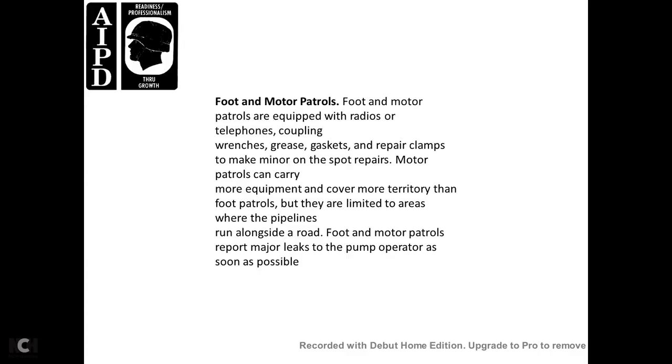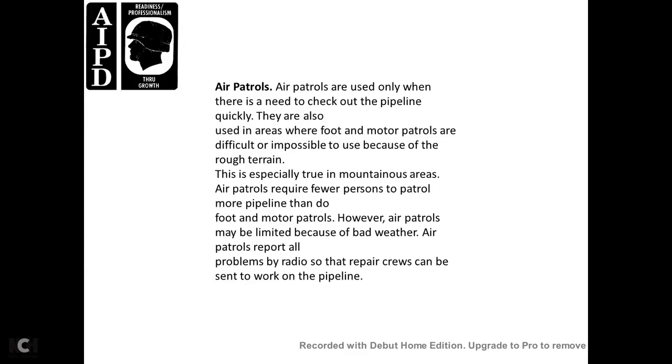Motor patrols are equipped with radios, telephones, coupling wrenches, gaskets, repair clamps, and minor spot repairs. Motor patrols can carry more equipment and cover more territory than foot patrols, but they are limited to areas where pipelines run along the side of the road. Foot and motor patrols report major leaks to the pump operator as soon as possible.